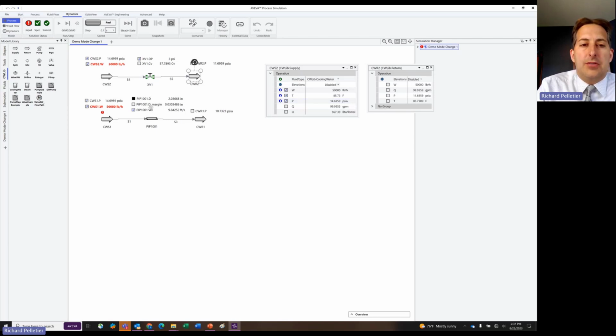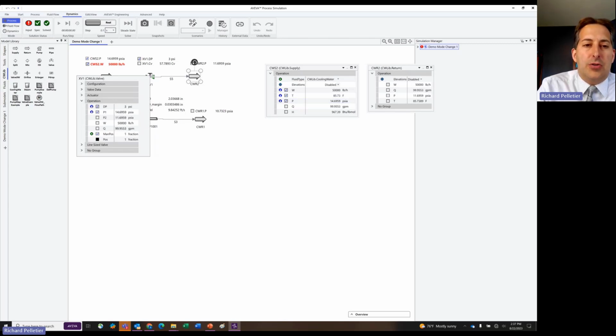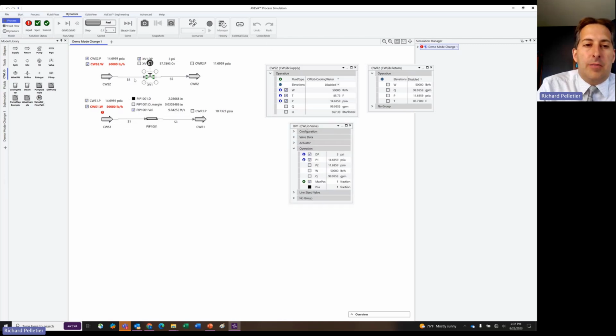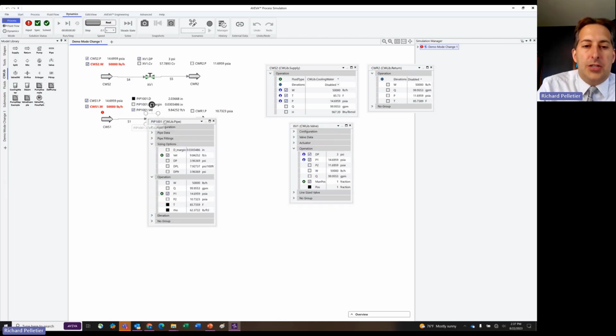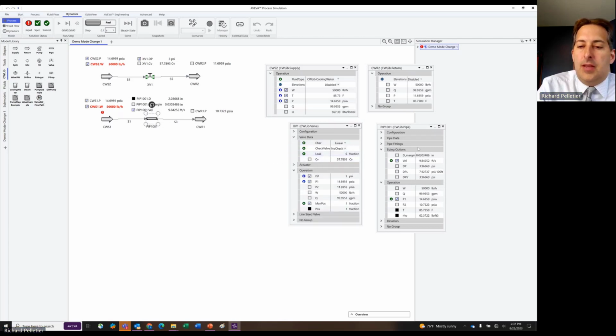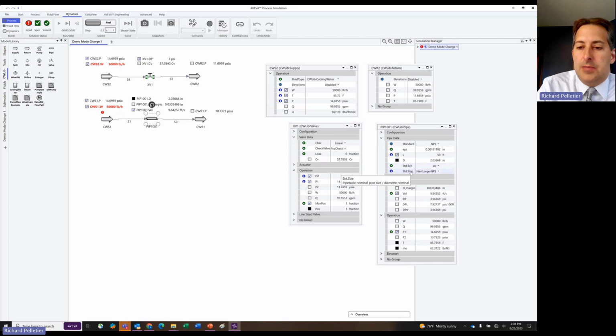And then I have two models here, and we're going to talk about why. But one, they're both pressure loss models, effectively. So a valve and a pipe, right? They're going to model our pressure change. All right. In the valve, we have the pressure drop specified, and it's calculating the CV. And in the pipe, we have the velocity specified, and it's calculating the pipe's size.